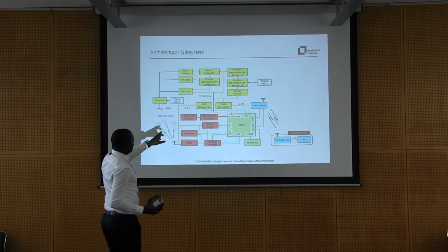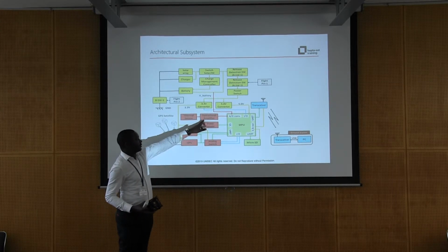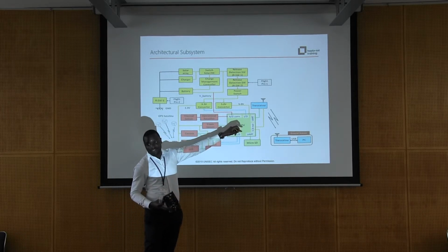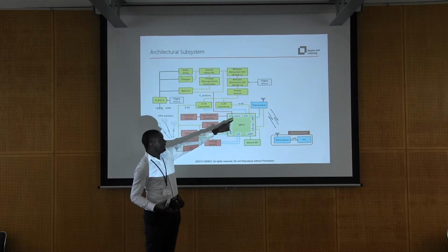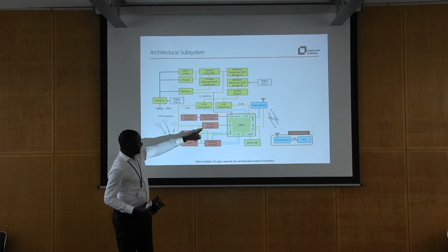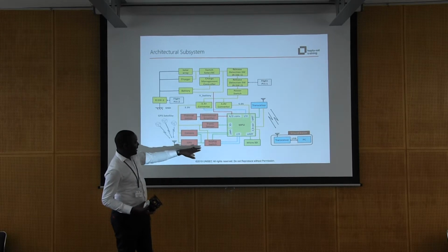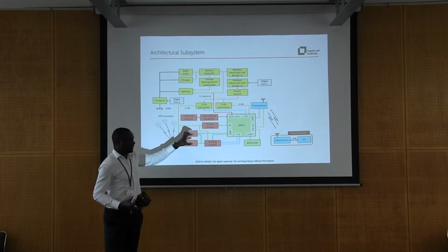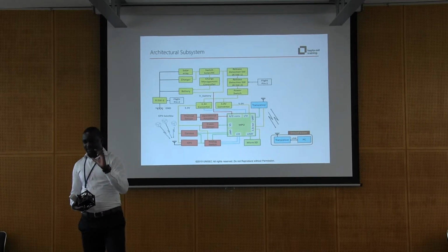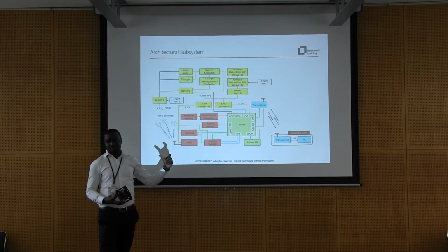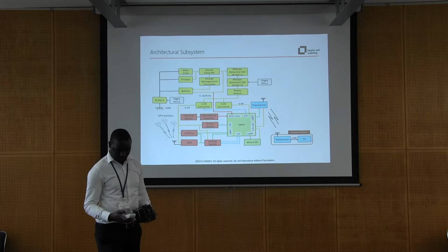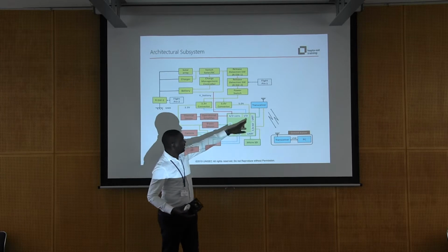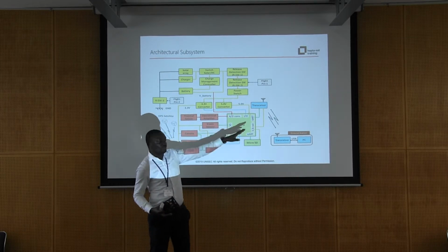And as you can see, the thermal sensor is an analog sensor, so you have to subject it to an operational amplifier, and then to the AD converter before it goes to the embed. The 9-axis sensor is already digital. The camera and GPS go through an analog switch because they are using the same port. So when you're taking the photo, the GPS is off. You take one at a time. And then for the next lecture, which is lab 5, you are going to see the installation of the blue part.